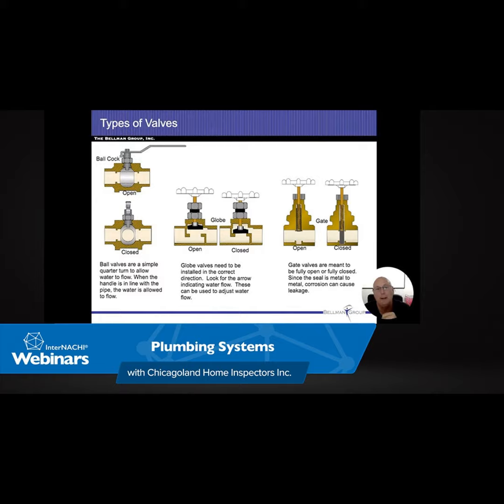So these are the problematic ones, things that usually end up causing clogs or causing them to be siphoned out for whatever reason. So starting on the left is a typical S-trap. Older homes, it was just very common. We never worried about venting all the sinks. We just vented the system when it came out to it, or the main soil pipes that came in there.